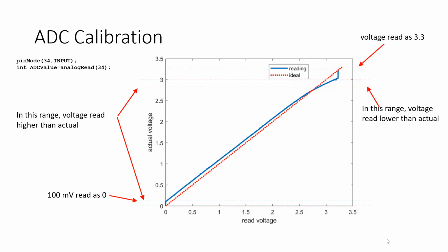They can very accurately set a voltage, because they have some kind of feedback controller in there that auto-regulates the voltage. So if you set them to 2.7 volts, they put out exactly 2.7 volts. The problem, though, is that if you're going to calibrate this, you have to calibrate it through the whole range. You can't just do 1 or 2 calibration points. You've got to calibrate a lot of points for this to work.